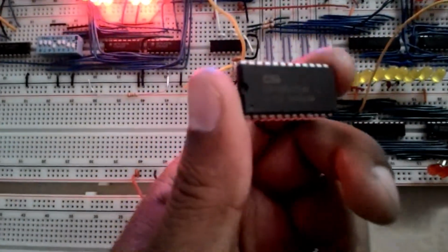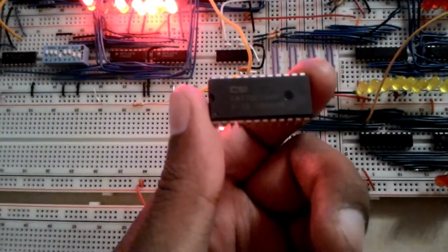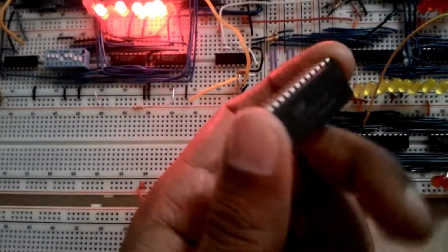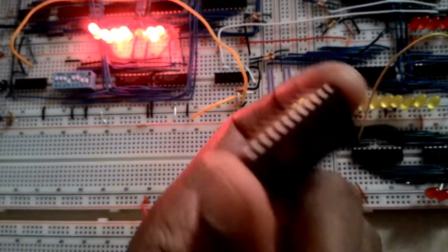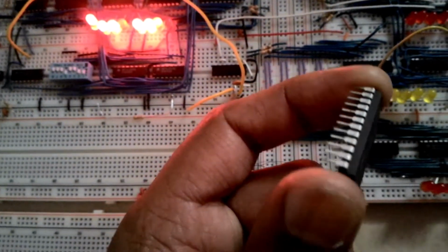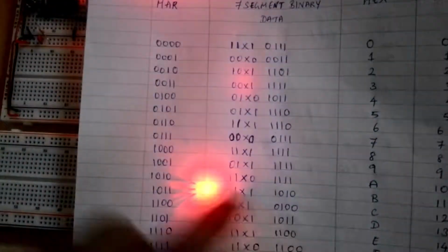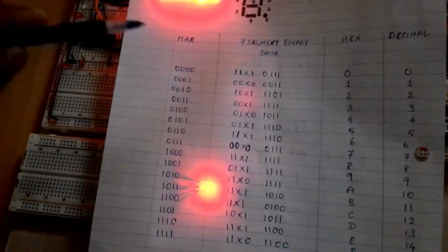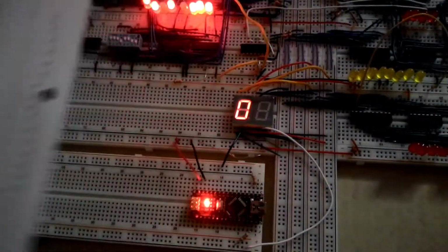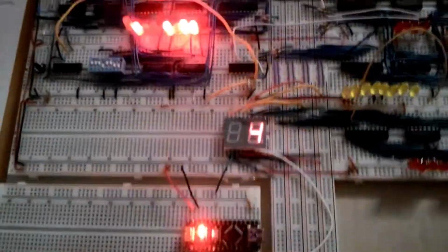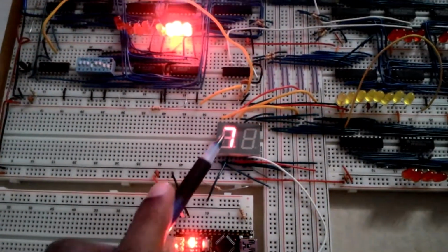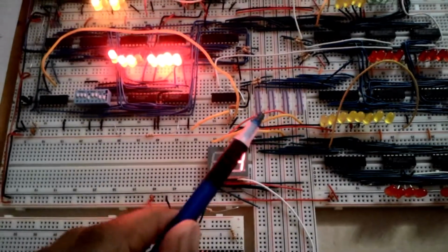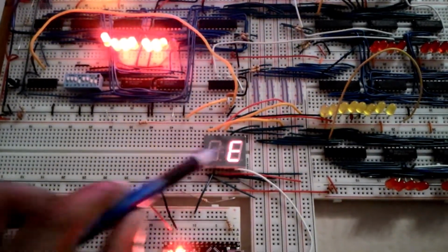and there is something like this programmable memory that I'm going to use, EEPROM. EEPROMs are nothing but erasable programmable memory chips, and this can store 8-bit data up to 2000 plus rows of data, and that is going to store the data of these binary values, and with the memory address like we did in our RAM, that is going to pull the data from the data storage registers and output the data, sorry, not to the bus, it is going to display the value in our hexadecimal display.